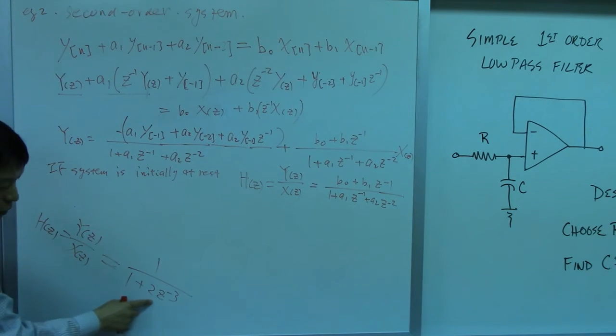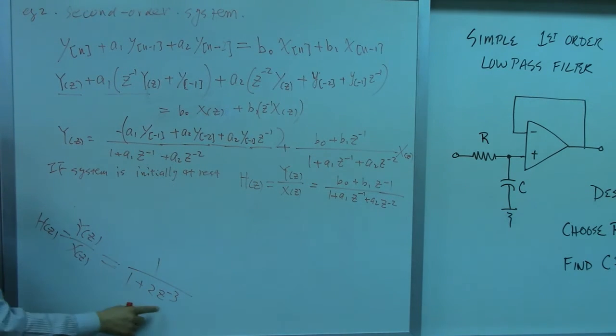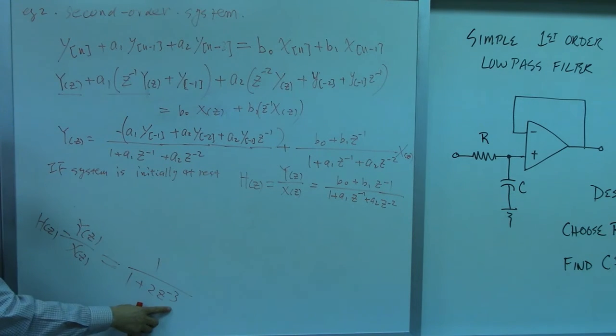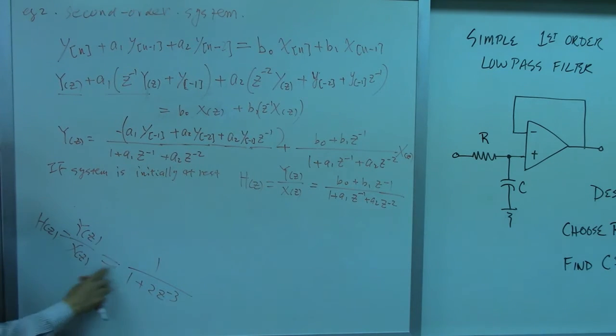And this one, 2Y(z) times z to negative 3. We mentioned z to negative 3 means delayed by 3 times. So this one is 2y[n minus 3]. And equal to X(z), this one inverse, just x[n]. Does that make sense?